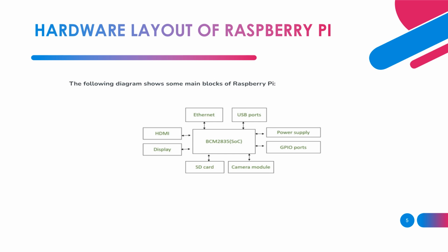Status LEDs. There are 5 status LEDs on the RPi that indicate the status of different activities: OK, SD card access, power, 3.3 volt, FDX full duplex LAN, LNK link activity LAN. Model B: Ethernet port is available on Model B and B+.